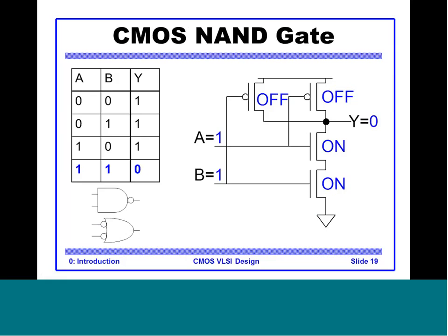So we see that CMOS technology is basically an inverted logic. That is, all the basic gates which are lowest in area and lowest in transistor count are either inverters, NAND or NOR. These are the basic gates. All other combinational gates are made out of these 3 gates. So if you remember your basic electronics, this is the reason why NAND and NOR are also called universal gates.